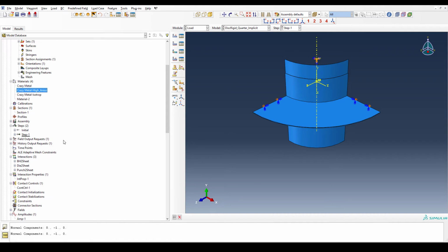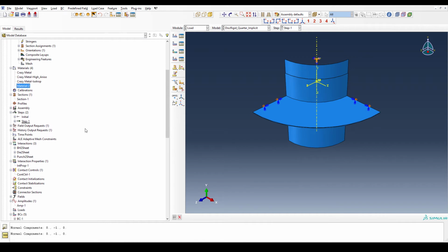So a couple of things we've changed compared to the previous videos, and you will find a lot of applications where, for example, the contact controls, if you want to go for an implicit simulation, which I recommend in most of the cases, right? The people nowadays, given the computational powers, just don't care about most of the things, just let me do dynamic implicit, because it has no convergence issues, right? We talked about this in video 6, right?